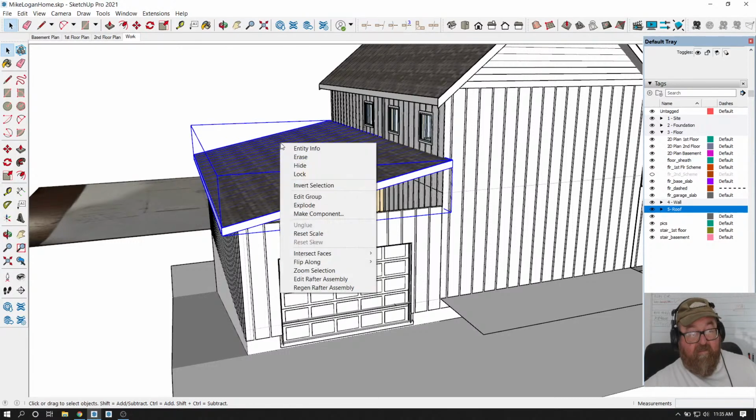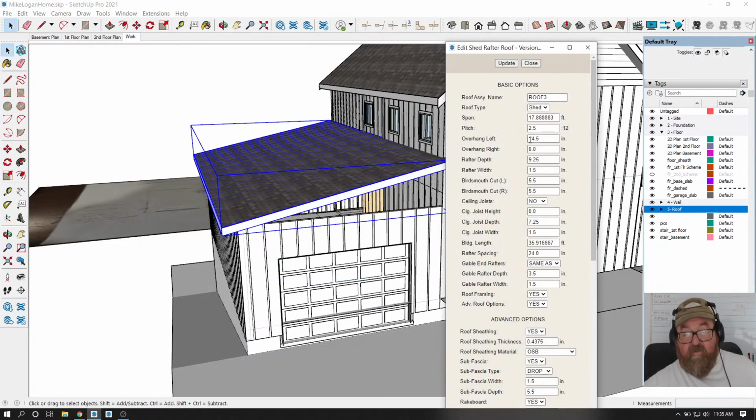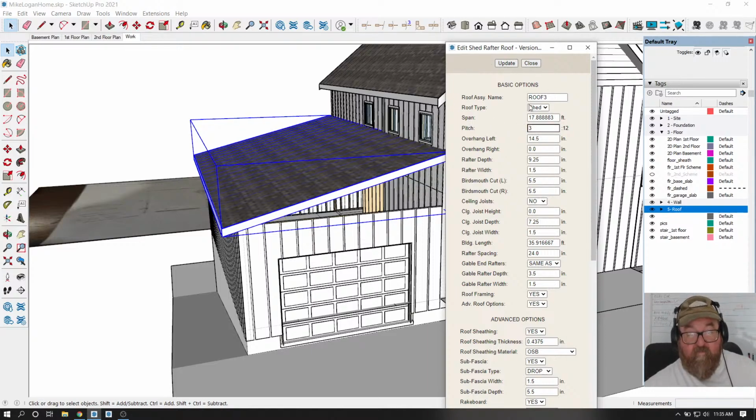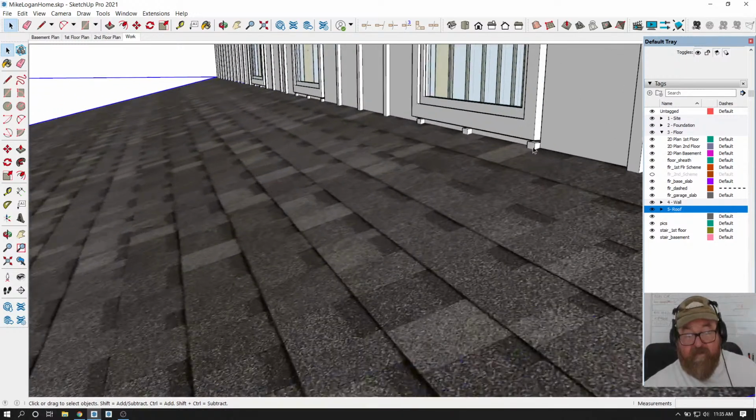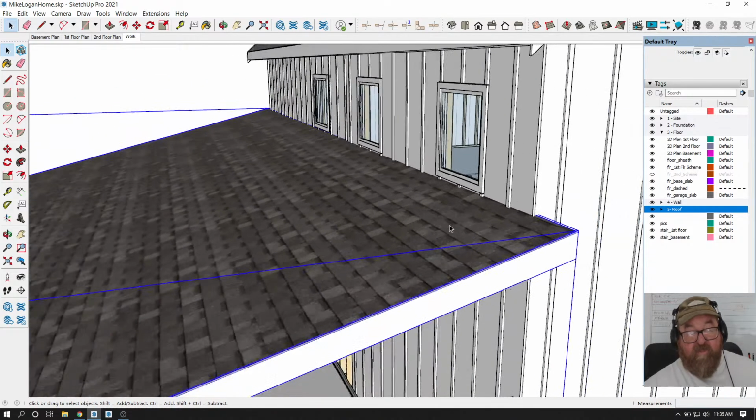Because if you raise it up any more, could make it a 3. But see, this gets weird because you can't make batten strips that small. So what you end up doing is trying to make this bottom piece of trim wider, and it sits on the roof, and it gets kind of weird.